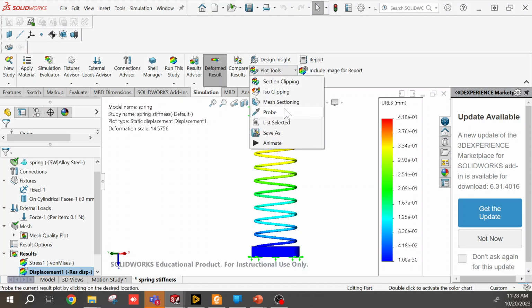Okay. And when you animate this, all it's doing is taking the first step and the last step and linearly interpolating between the two, saying I'm inserting 150 images in between, and that's all it is. When it's a linear analysis, it can do that quite easily. When it's a nonlinear analysis, it has to actually solve every step of the equation. So it's moving a small amount, solving, moving a small amount, iterating a solution. In this case, it's just a single step.